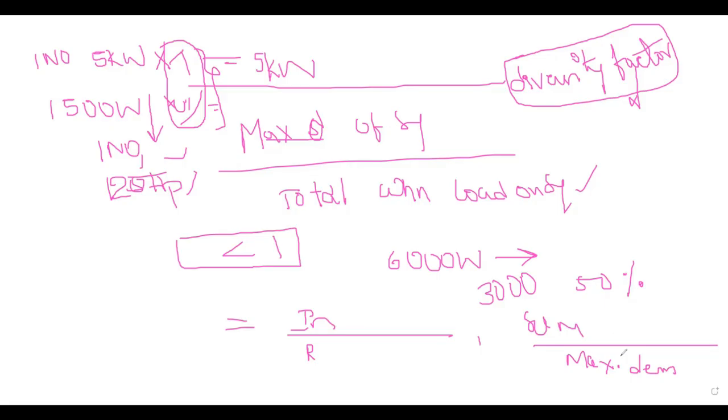Generally, if you look at distribution networks, we have many different types of diversity factors. If you refer to the standard IEC 60439, you can find diversity factors for different cases. For lighting and for sockets, they have their diversity factors. Suppose you look at apartments: if you have 20 houses in the apartment, then it is recommended to take a diversity factor of 0.49.